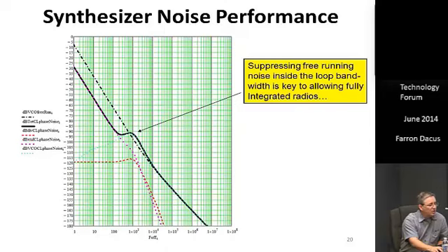And then once you put it in the loop, you will get some changes. For good quality VCOs, the resistors in the loop filter generate enough noise that you'll see them. If you have 1K ohm resistors, that is enough thermal noise to degrade a high quality VCO. Noise on the power supply will come through as well, because both the power supply and the input noise modulate the VCO, and that modulation shows up as phase noise.